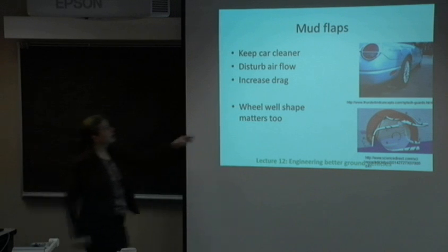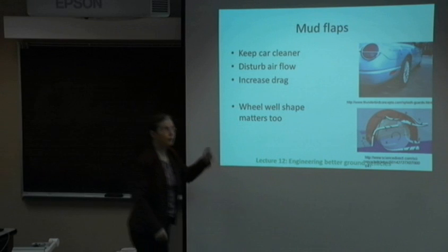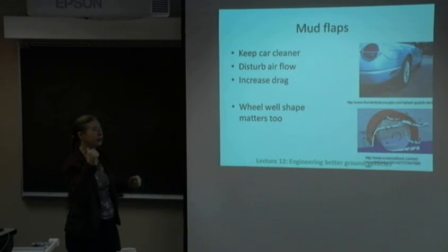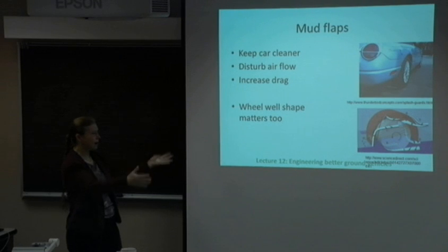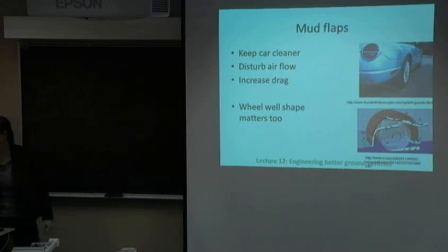And actually, even the shape of the wheel well matters. I don't know if you noticed in that wind tunnel, I don't know if it's that one or another one I'm going to show you shortly, the wheels are turning. And you say, well, what's the point of them turning? The car is in a wind tunnel and it's in a fixed position, but the rotating tires will affect how air moves through the wheel well. So even that can have an effect.